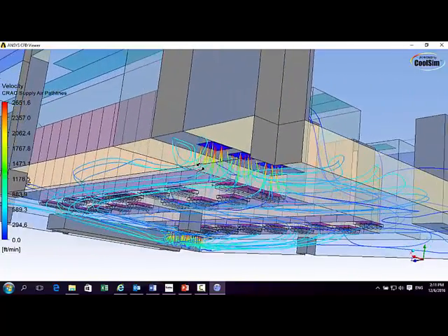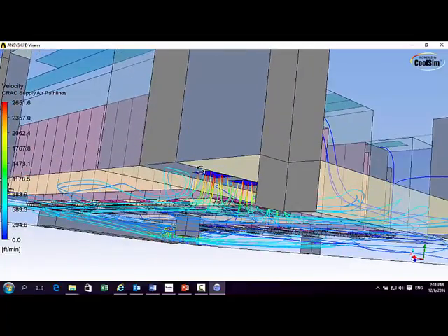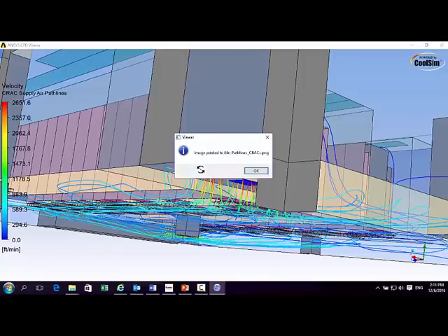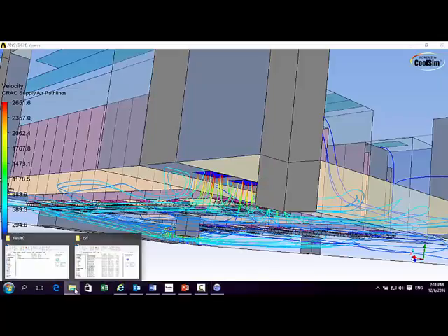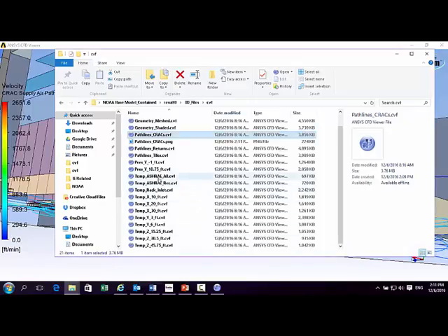This in fact is technology produced by the Ansys Corporation. And if I simply hit a P key here, it'll generate a PNG of that image in the same aspect ratio as the one I'm looking at right now, and write it right back into that same directory. So if I go back to the directory I was just in, there'll be a PNG sitting right there.